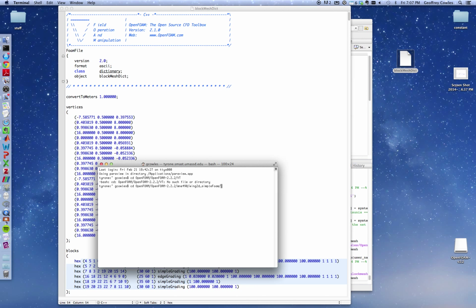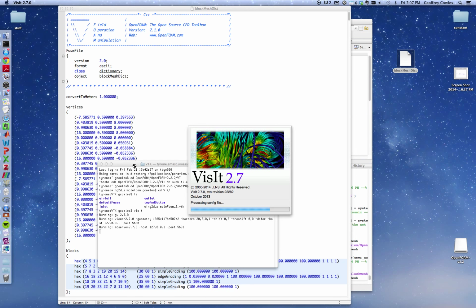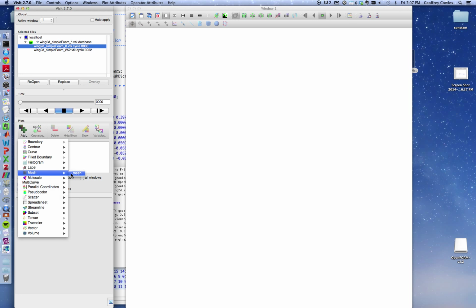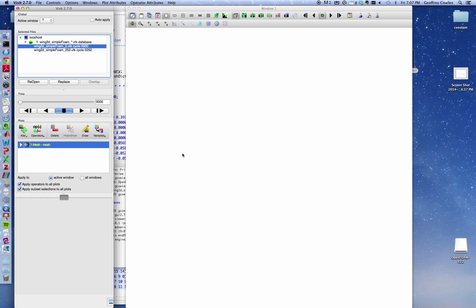So this would be in a later computing assignment. You're going to use OpenFOAM to compute flow over a wing, this 2412 wing, at a given angle of attack. And one of the input files OpenFOAM needs is to describe the mesh, and that's what that Matlab code generates. So open this, and then I'm going to add the mesh and draw it. I may have to slice it.